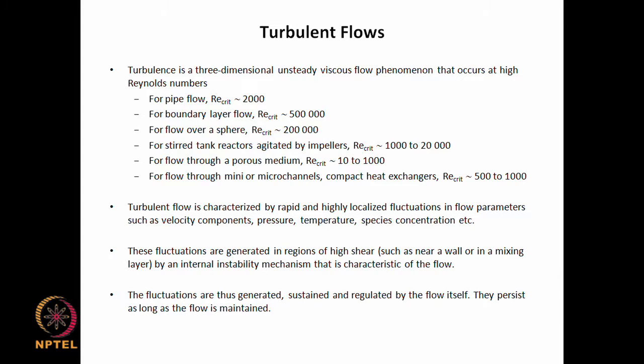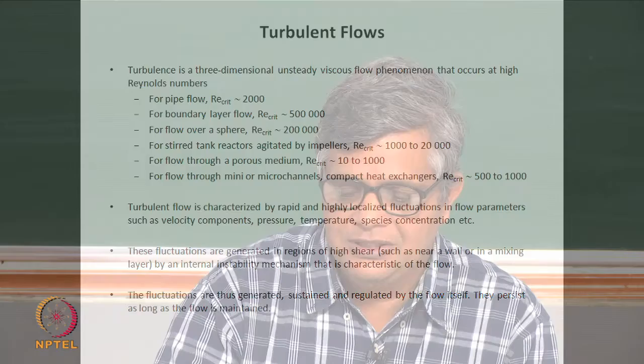So it is not like flow over a flat plate where the physical dimensions of the fluid domain are infinite, and similarly flow over a sphere, where you have an isolated sphere in an infinitely long and wide medium. So for all these cases it is difficult to precisely say this is the Reynolds number beyond which you have transition to turbulence. Typically anywhere between 1000 and 20,000 can be a transitional regime, and beyond 20,000 or so one would expect the flow to have become fully turbulent.